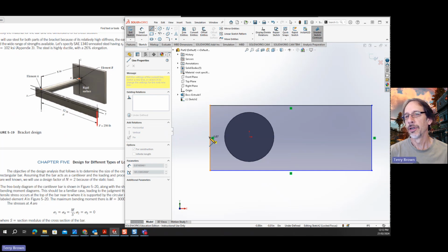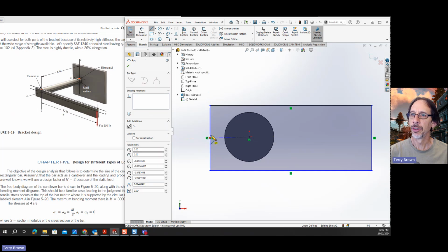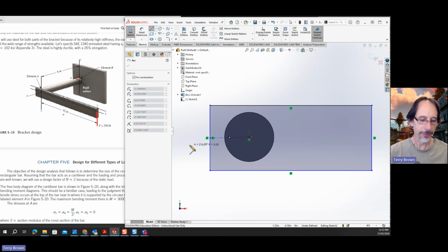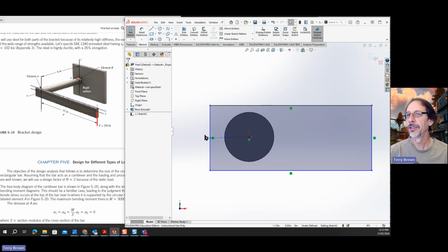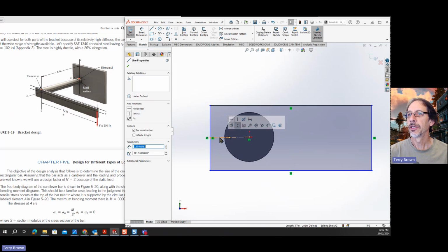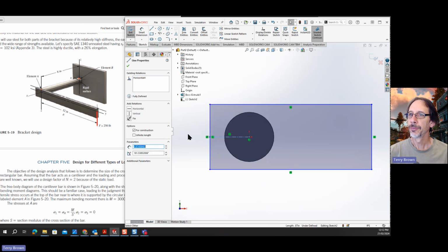There it is. The eraser end of the pencil is covering the little icon there. But just make sure after you've clicked that you've got the midpoint constraint, not just constrained to be on a line. So if we exit out of that and click on that and make it horizontal,